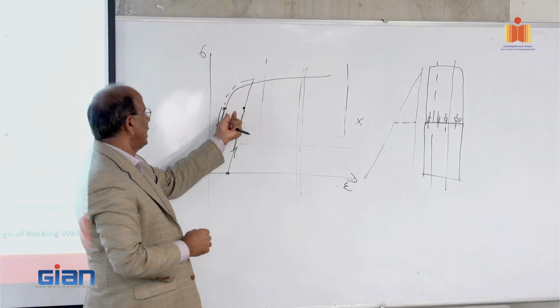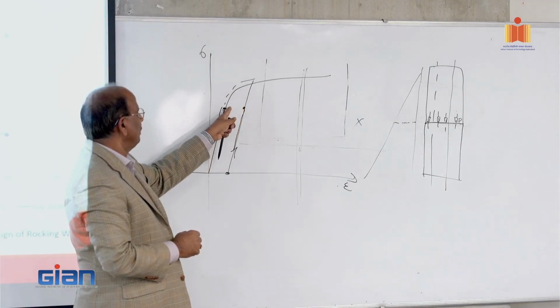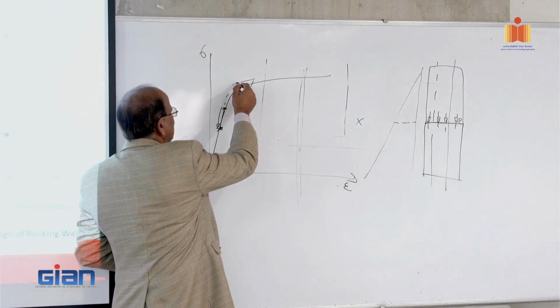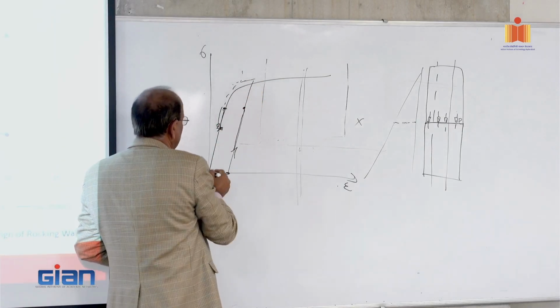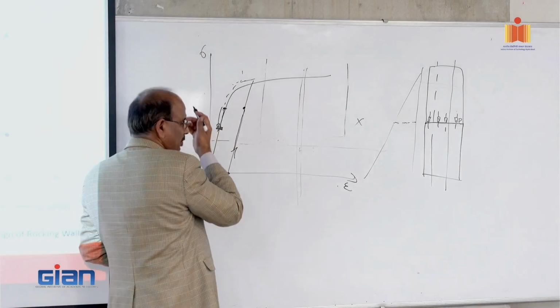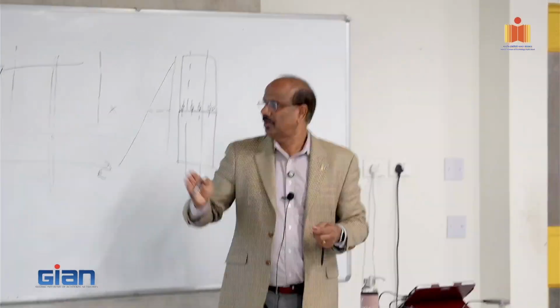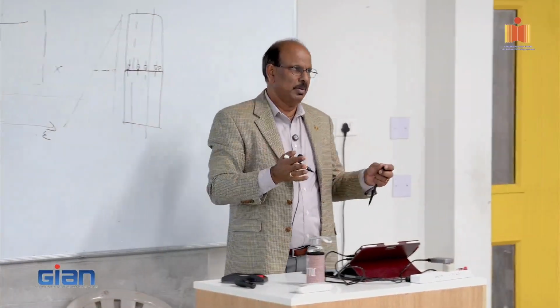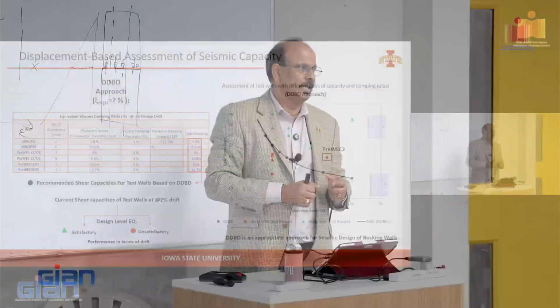So the question is, how big is it? Can you tolerate this value? What we have done is some studies to say if this goes into the plastic range, or if you lose, I can't remember the number, is it 10 or 15%, the structure will survive. So if you lose 10%, 15%, you're in the curved portion of it, maybe it's acceptable. But if it's significant, then you have to replace the tendon.